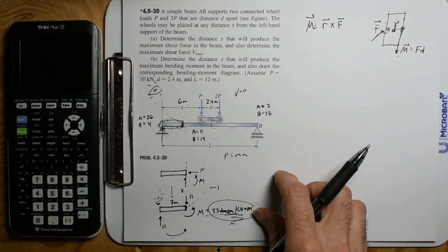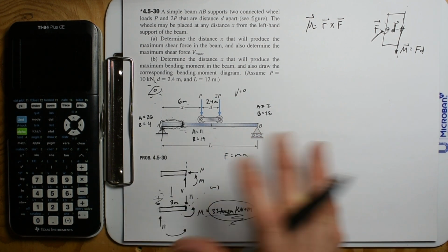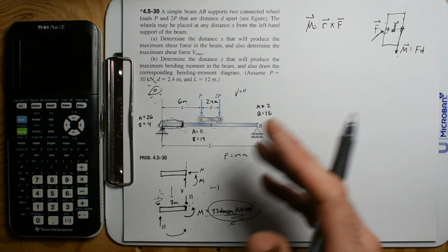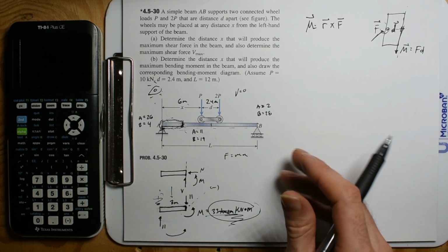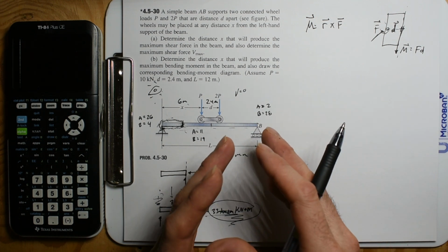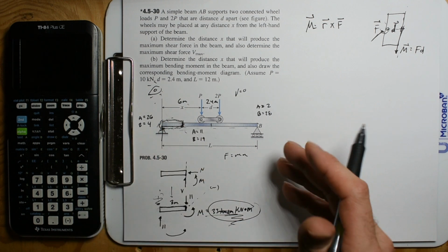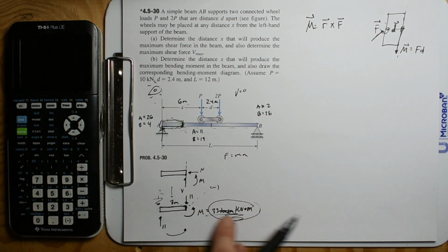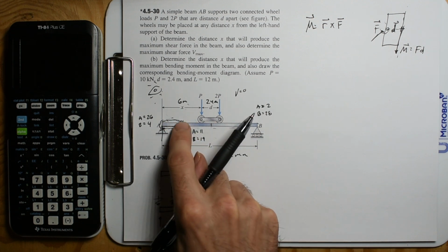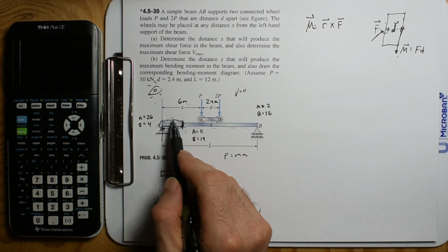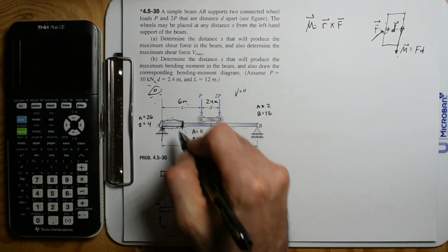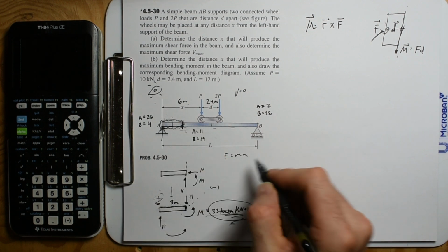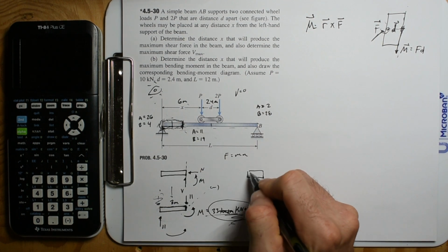The way that I like to do things is just do a bunch of simple problems, because then you kind of get an idea of what's going on, where then you could actually make an equation, solving for all values of x. You could figure out the moment for all values of x. We just took this slice at 3 meters. So now let's take the slice at 1 meter. So we're going to come in here, have a 1 meter slice.